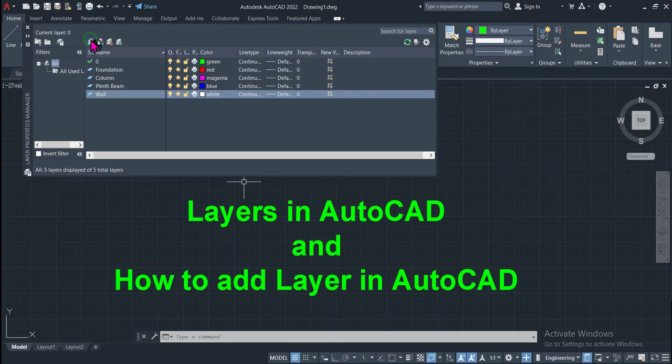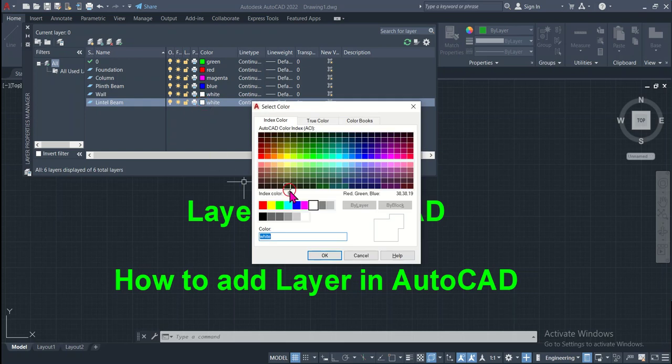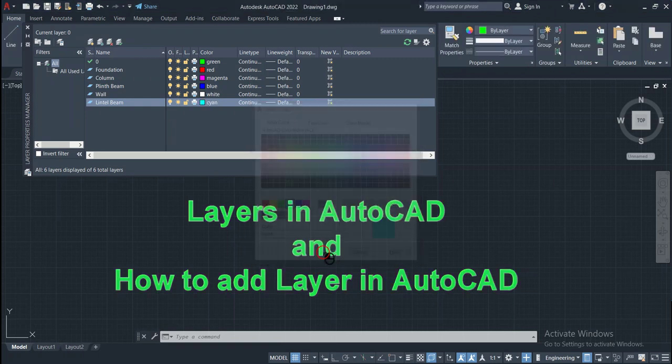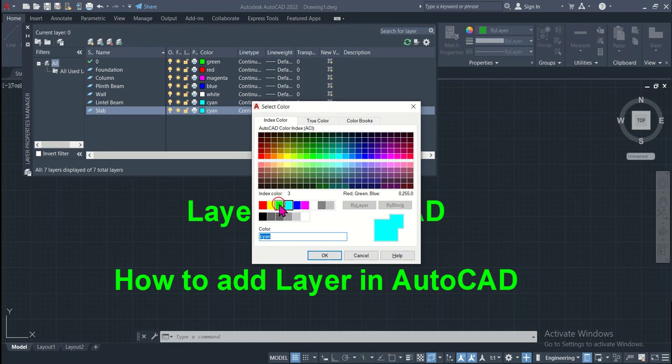We can add another layer and name it lintel beam, and we can change the color from this color. A color has been assigned to this, and we can add another layer. We can name it slab, and we can assign it a different color.